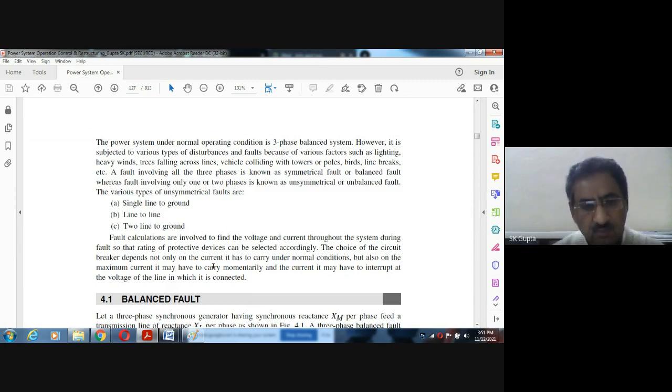which will make the transmission line open when the circuit breaker receives the signal that the fault has occurred, from the relays. So relays are those devices which actuate the circuit breaker by sensing the fault, and then the circuit breakers open. Now the question is, during the fault, what is the current, what is the fault MVA that will be there for the circuit breaker.